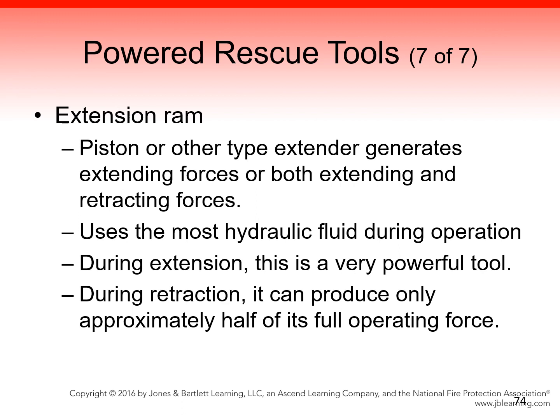It uses the most hydraulic fluid during operation, so the pump being used must have enough capacity to allow the ram to reach full extension. During extension, this is a very powerful tool. During retraction, it can produce only approximately half of its full operating force. These tools are extremely powerful and should be used only by firefighters who are properly trained in their operations. Always reference the manufacturer's operator's manuals before use.